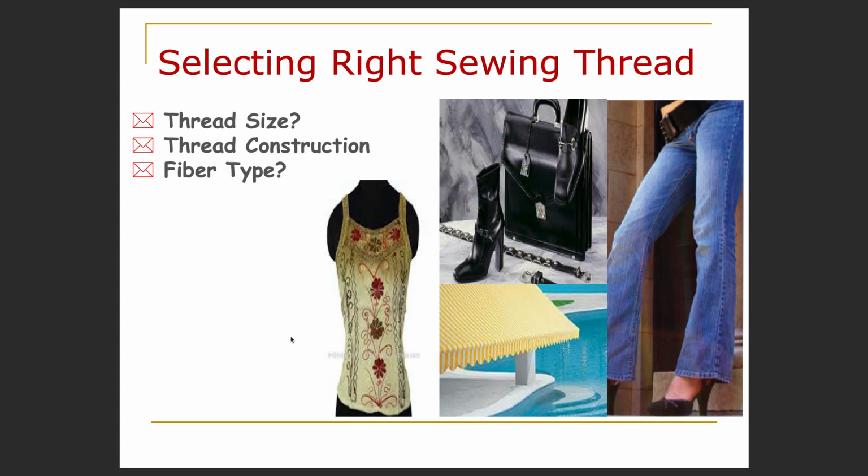So if we use a sewing thread which has S twist, the Z twist imparted by needle will tend to open up the sewing thread. So in order to avoid it, we prefer the use of Z twisted sewing thread on the lock stitch sewing machine, so that the Z twist imparted by needle does not open the sewing thread if it is S twisted.